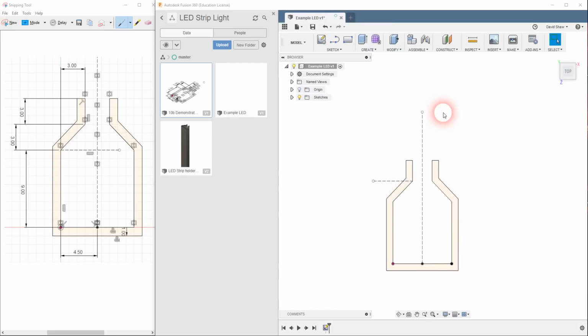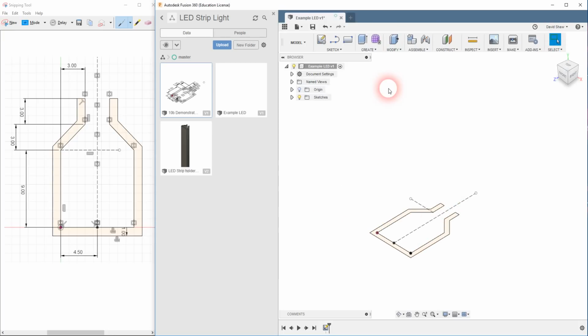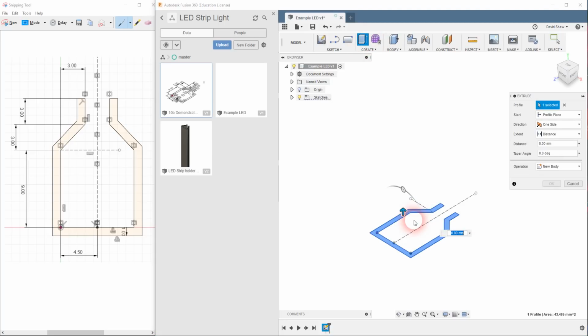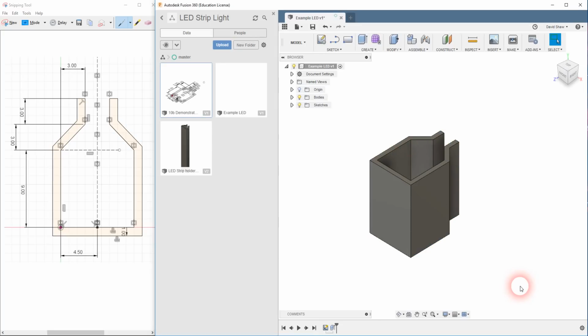Let's just stop the sketch there. Let's go into the 3D view. There it is, that's on my top plane, and I'm now going to simply go to the extrude option. I'm going to select the profile I want to extrude, and then I can extrude that up to whatever height I want it to be, and confirm. I will just actually mention two more things.